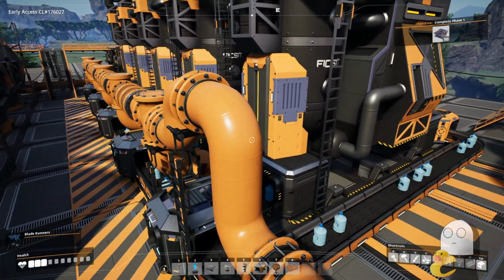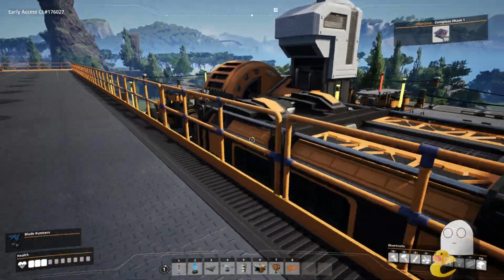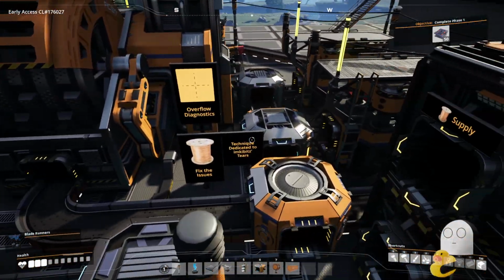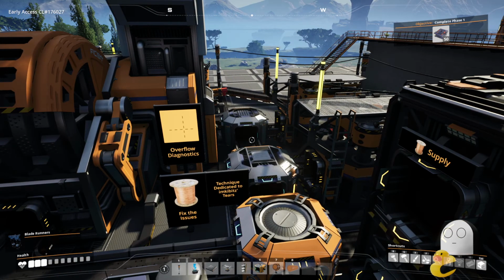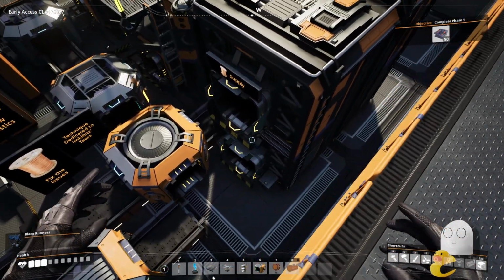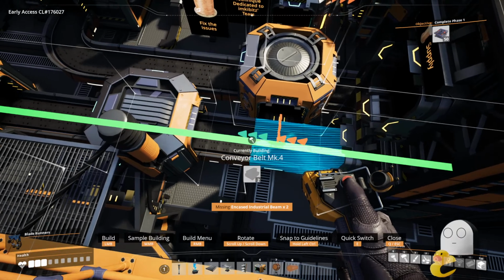The other use for this technique is for diagnostics. Say you have everything load balanced, you're going to use an exact number of parts. You have it set up all beforehand. You know you're not going to have any waste. But you can't tell if anything's wrong until it's a few hours into the process and stuff is backing up. There's a way to do that with the overflow function or an overflow pipe, in that if anything doesn't get consumed, it will be overflowed and you can visually see where it is going.